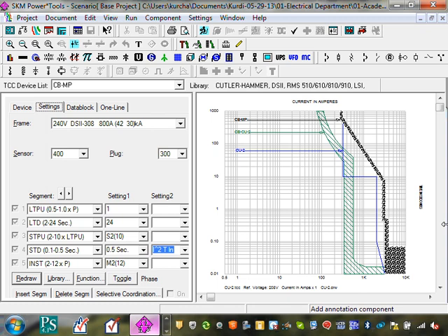I can reduce that. In this case, you're looking at a 100 amp, an 800 amp frame adjustable circuit breaker. A frame, guys, is a box, a drawer. How big of a box can you fit? That's your frame. Inside this box, the maximum is 800. I stick in a sensor, these are your CTs, 400. I don't want to take the full 800. Then inside the sensor, I can plug my circuit breaker in.